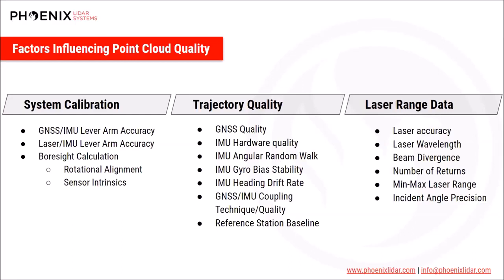In addition to the actual hardware on the rover while flying, our reference station is also of utmost importance. This base station that would sit nearby our project provides observation corrections for the rover. And so if this base station is logging incorrectly or is very far away, these observations are not corrected as much as they could be, thus degrading the point cloud quality.